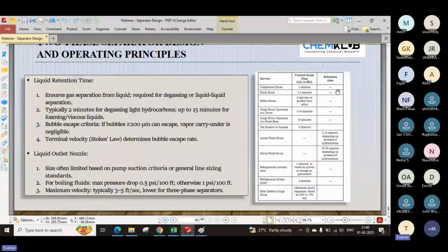You can divide these time limits as per your own convenience, or based on the company guidelines for whom you are preparing the engineering documents. When you are doing any separator sizing and you do not have any criteria, you can follow the GPSA equations or GPSA time limits given for that particular application. Even if you are doing any retrofitting, you have to ask for the time limits they considered initially while sizing the separator. That will give you an idea about the requirements. So this is what we have for the separator sizings.